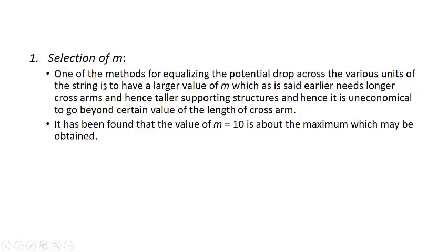In this case, we may use disc insulators which will provide a higher value of capacitance as compared to the capacitance of the metal parts of the insulator to the ground. This can be achieved by using insulator material which has a higher dielectric strength, or by increasing the distance of the insulator string from the tower structure.